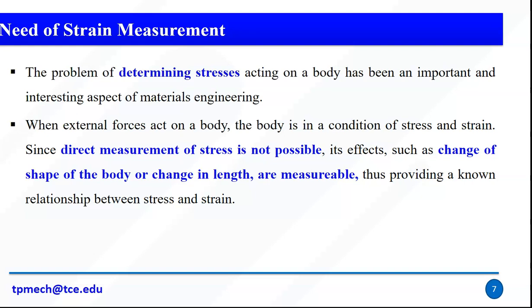If the stress is below the elastic limit, the strain will be regained. The change in length will come back to the original. If it is in the plastic range, it will change to a permanent shape change. If it goes more than the plastic shape, it will break. So since direct measurement of stress is not possible, stress is a very important factor, but we can't measure stress in a direct way, but we can measure the causes of stresses.